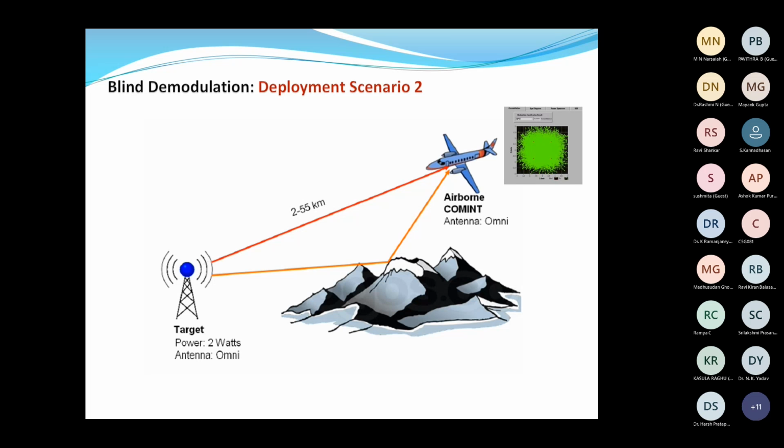When we finally process that signal, within the observation interval there will be a variation of the parameters. So this again required the scheme that we proposed in our previous slide. For mitigation, we employed a cascading scheme of MCMA and modulation-specific DDLMS, followed by QHLRT modulation classification. To see the results is very interesting. Although the theoretical results say something, we have something slightly different from the theory. This is because a lot of unknown parameters come into the picture when we deploy systems in these scenarios, and sometimes it is very difficult to predict why there is a deviation between the theoretical results and what we practically see.